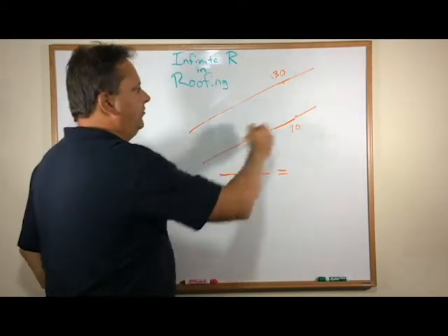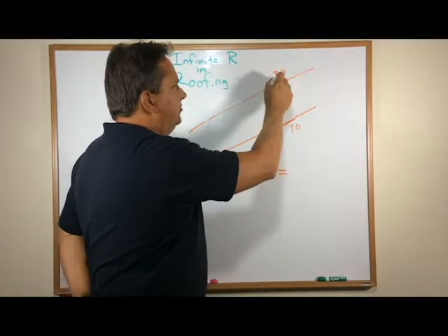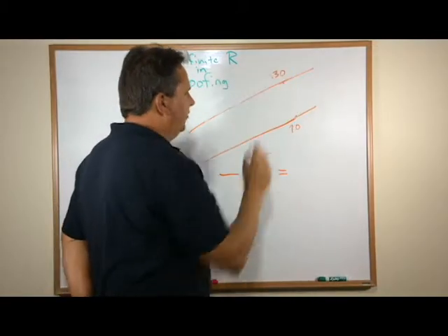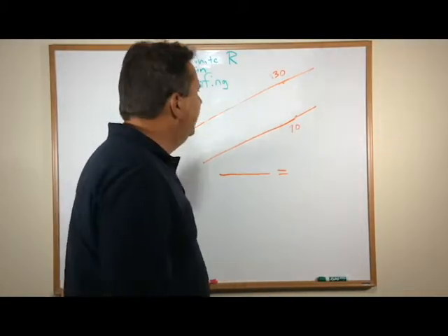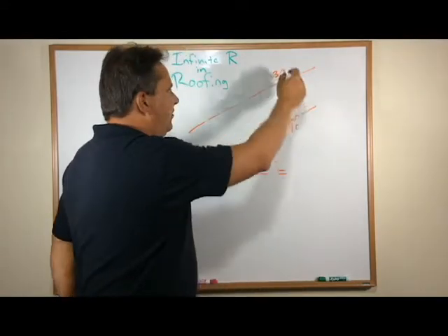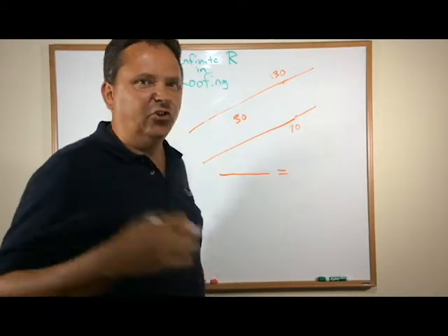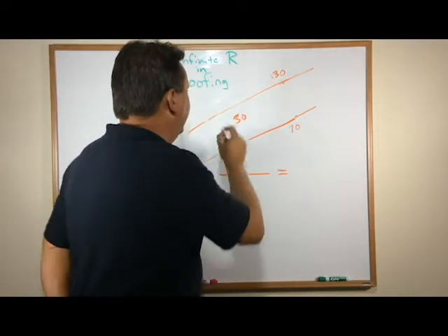Let's say we have a roof structure. Let's say it's the middle of the day, so the temperature of the roof surface is 130 degrees, and the inside conditioned space is at 70 degrees. Let's assume that we have an R value across here of 30. A really nicely super insulated roof, like an R30 SIP panel.